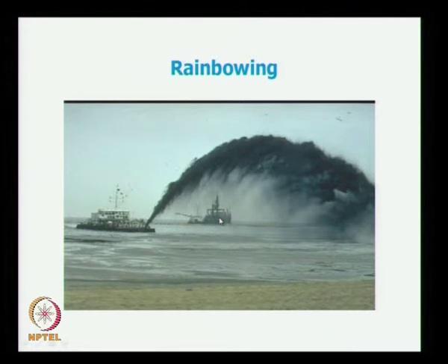This is called as a rainbow method. So what they do is from the dredger they put it on another vessel or the same dredger will come here, then they pump it like this, about 300 meters it can go and then pump and then it will stockpile. So groin number 2 to 11 they will be doing this rainbow technique. So here groins are there, sea walls are there, artificial nourishment by pipeline as well as by rainbow technique.